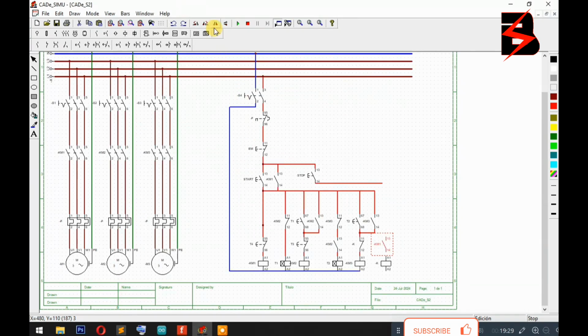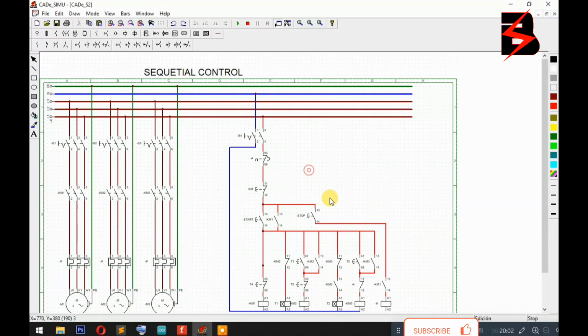So I'm going now to complete that cable of mine so that I can also feed my relay. I've powered from the power through the stop. Stop is normally open here. Then through the normally open of contactor 1, then to the relay. So this K relay is going to self hold itself from somewhere here, like that. So this one here is a joint.